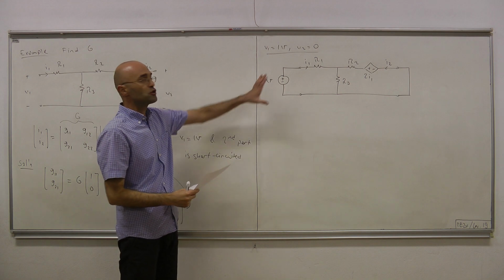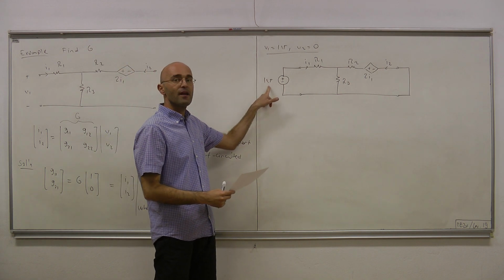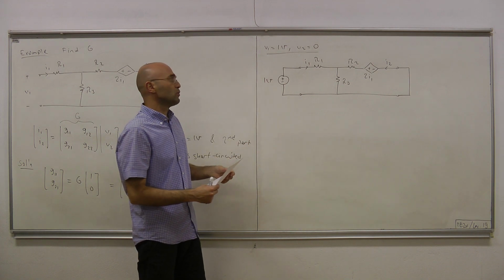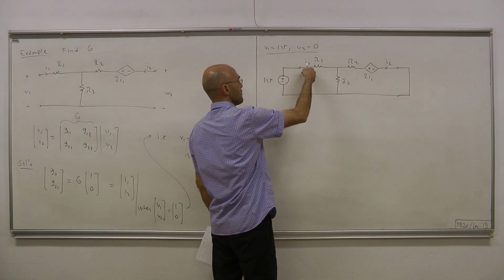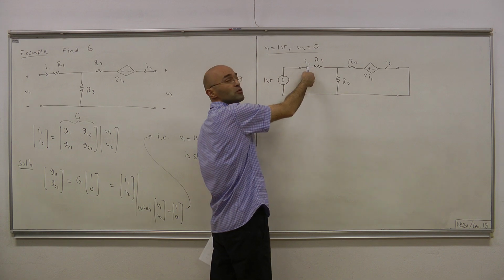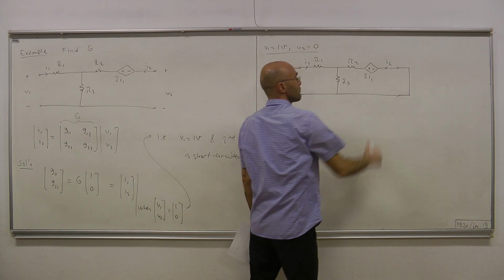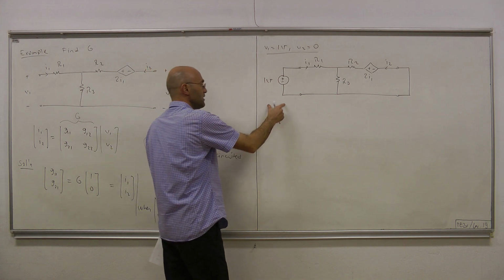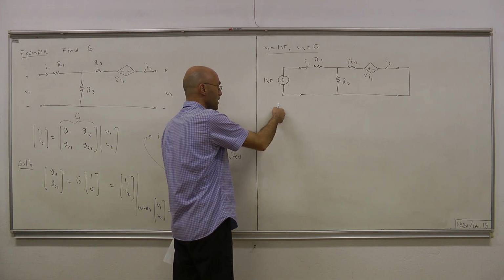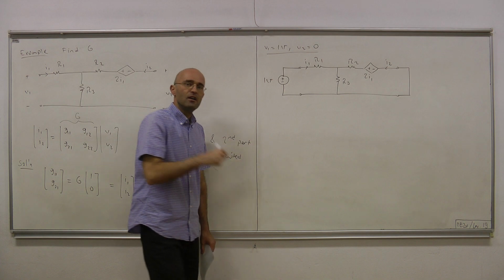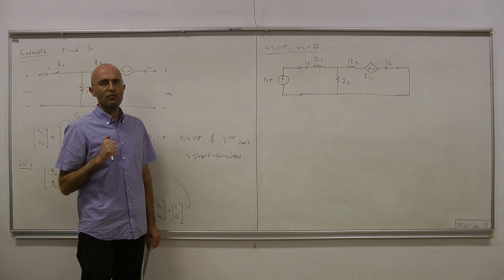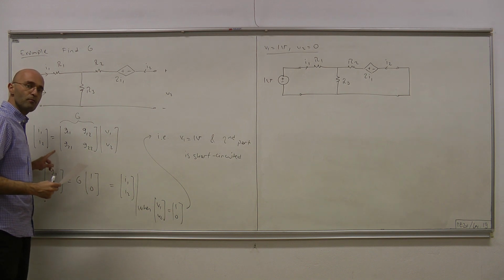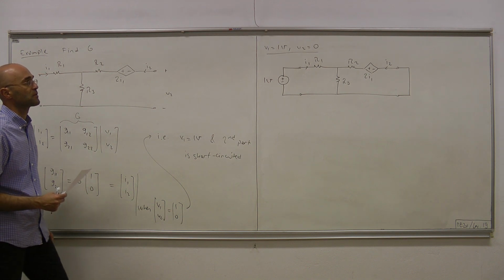For this situation where we have just this single input, there will be some current and voltage throughout the circuit. Now, you compute the first current I1, you do the same thing for I2, and then bring those two currents together in a vector, I1 here, I2 here, and that vector is the first column of your conductance matrix, which directly follows from the definition of the conductance matrix.